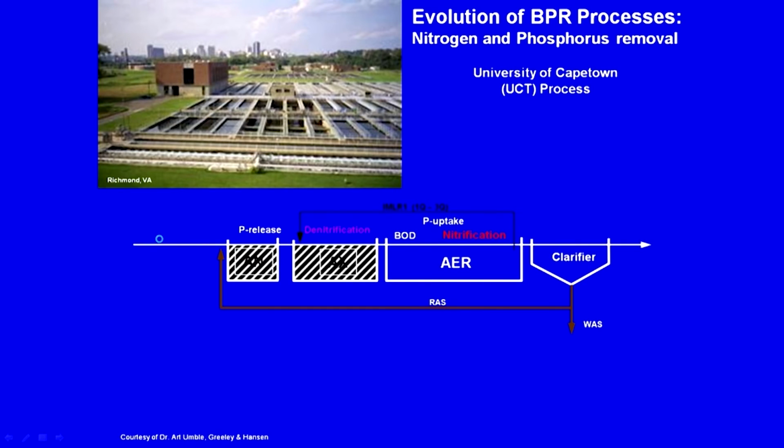So, this is what we looked at until now, right, but the issue was that here the nitrates, if any, or those which might be present in this waste or return activated sludge will affect the phosphorus accumulating organisms here, or phosphorus release here. Without phosphorus release, they can't store the PHBs, let us see.